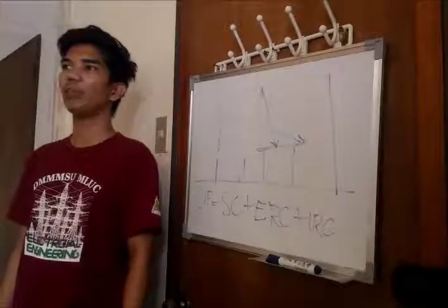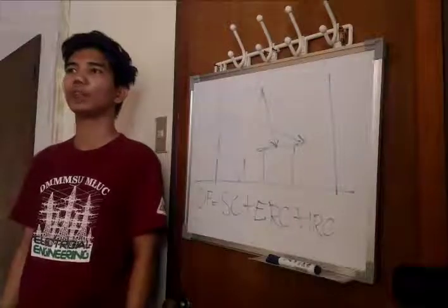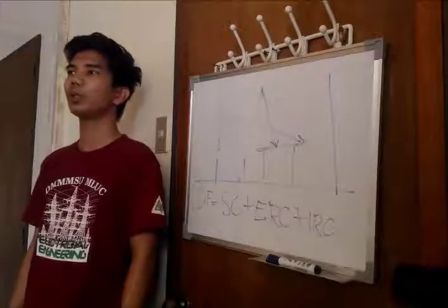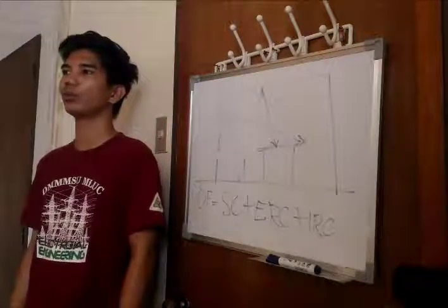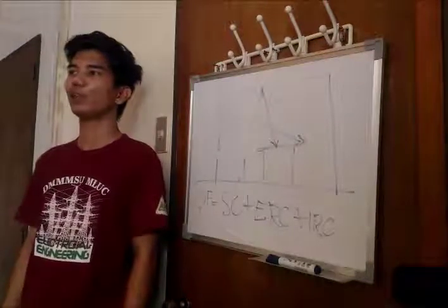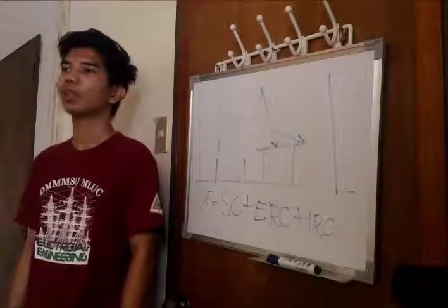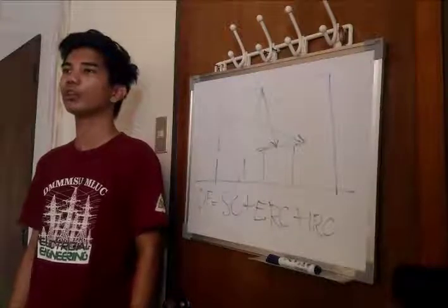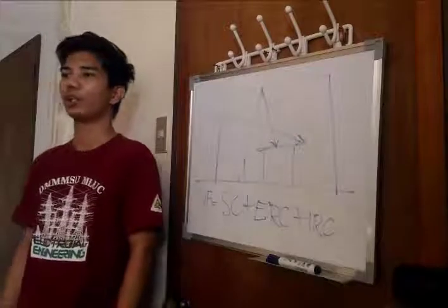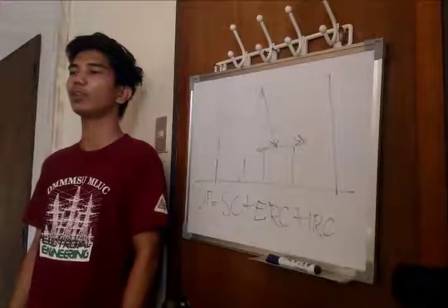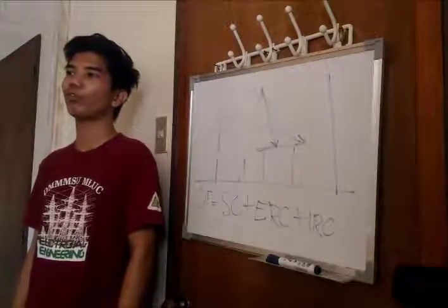In glare, the aim of an efficient daylighting design is not only to provide illuminance but also to maintain a comfortable and pleasing atmosphere. Glare, or excessive brightness contrast within the field of view, is an aspect of lighting that can cause discomfort to occupants. The human eye can function quite well over a wide range of luminous environments but does not function well if extreme levels of brightness are present in the same field of view.